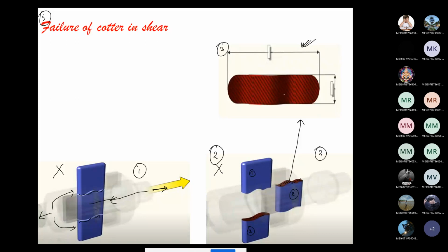Now see this one, the failure area appears as a rectangle, right? Shear is happening here, so shear stress is induced. Shear stress means the basic equation, force by area. So F suffix S equals sigma S into A. What is the A here? The A is the failure area. The red color hashed line is the failure area. I'm writing the area for this one.